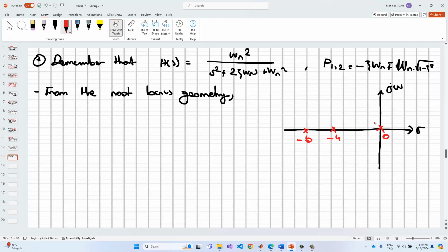And so we know that we have the one desired point in here, and the real part of the pole must be equal to minus 3.613, right? And so we need to add the j term, but we don't know the Wd value in here. How can we obtain this value based on this information or the geometry of the root locus, okay?